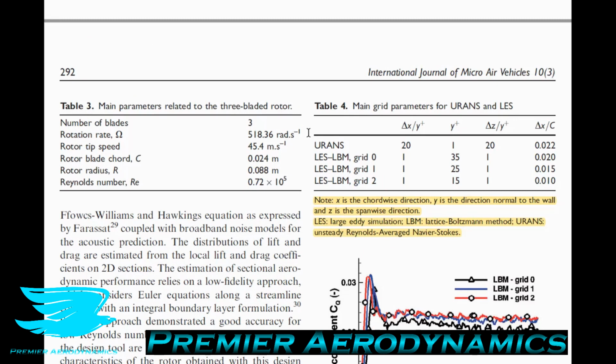And the thing with the LBM method, as I mentioned in the first podcast, number 85, is that when you discretize the domain, you pretty much have to do it just linearly. So it's all uniform. It means that when you have very fine details, if you want to resolve those, if you want to effectively mesh them, it's not technically a mesh, but I'm just going to call it a mesh just to help you conceptualize.